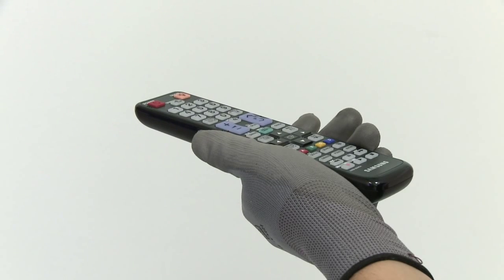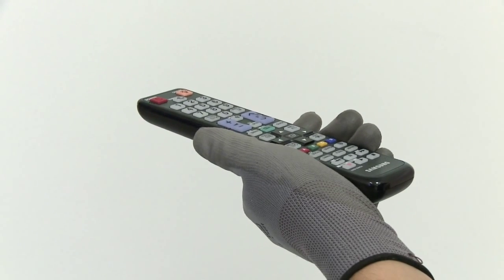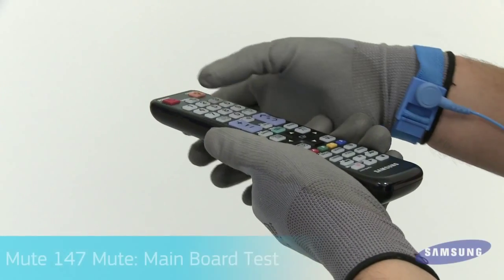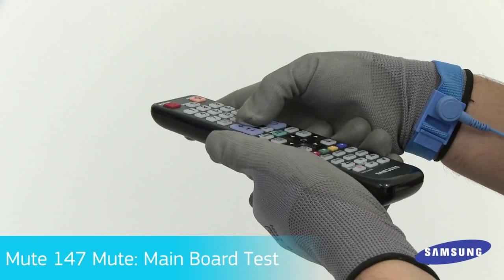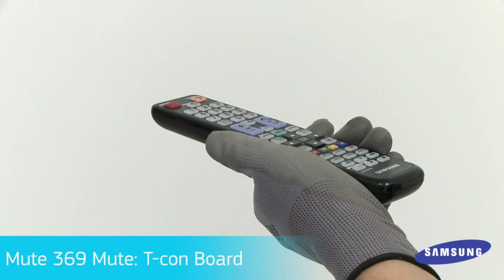Now, in some cases, if the on-screen menu is distorted and you cannot access the picture test, you can simply press Mute 147 Mute or Mute 369 Mute to bring up internal test patterns. This will depend on the model. These patterns coming from the main board and/or TCON board will display for 5 seconds, and you can check for any defects.